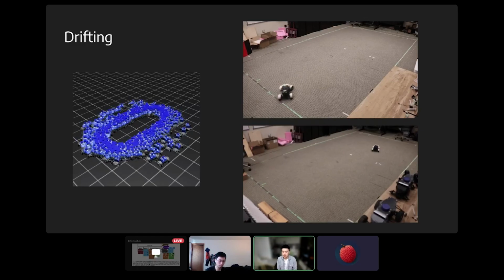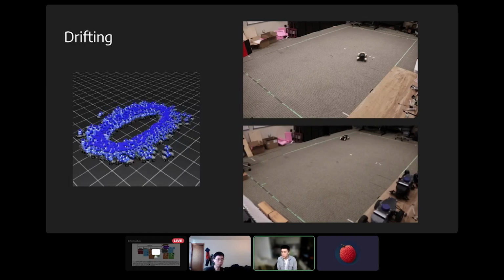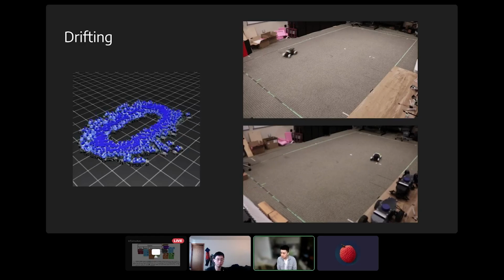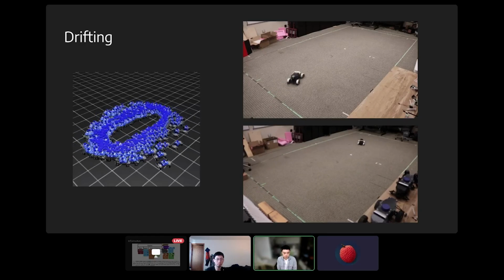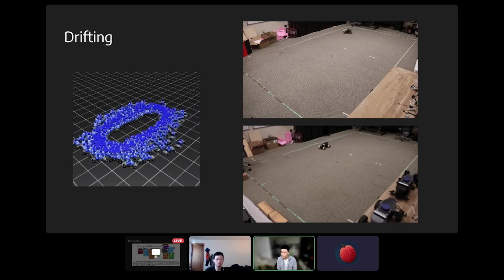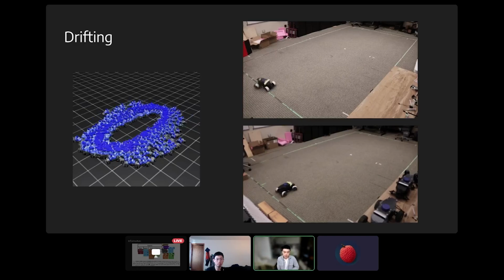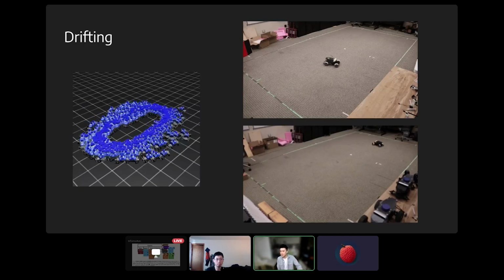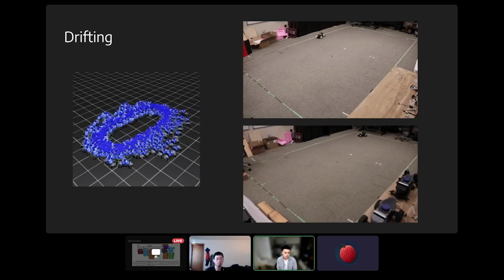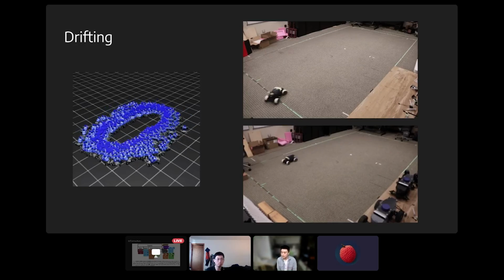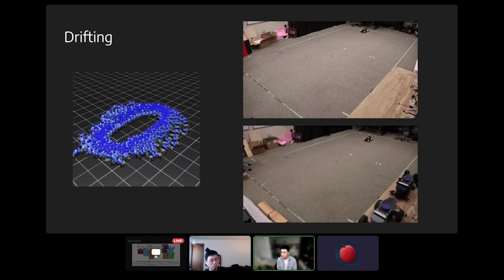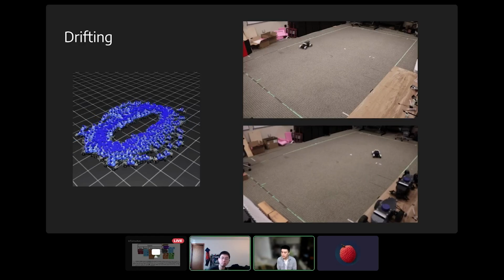Yeah, so we basically corrected the steering linkages and added in suspension, which happens to be another prismatic joint with a P gain. I found that interesting because right now there's nothing in Isaac Lab that supports something called suspension, so we had to add in another joint. Okay, interesting. But yeah, these things were mainly made to make the drifting tasks more accurate.